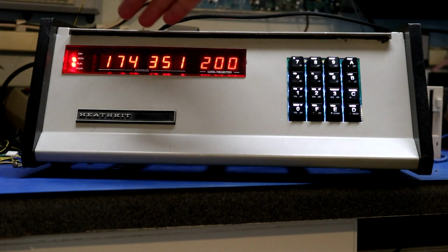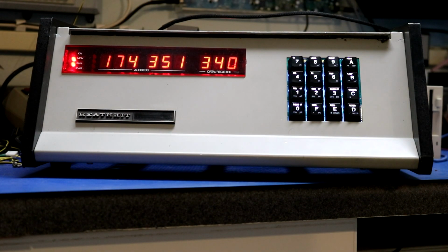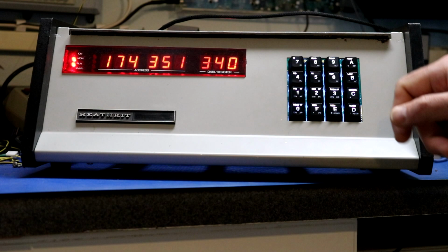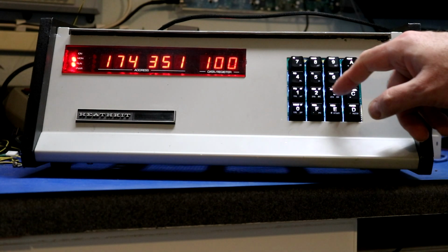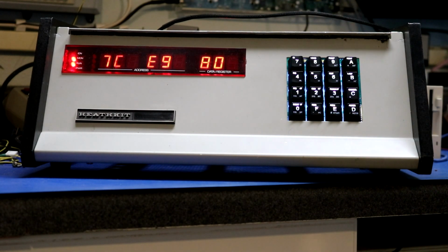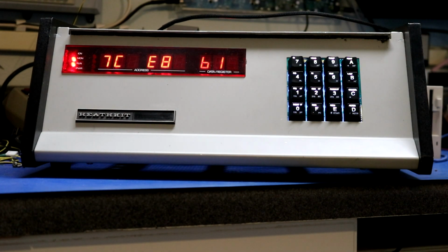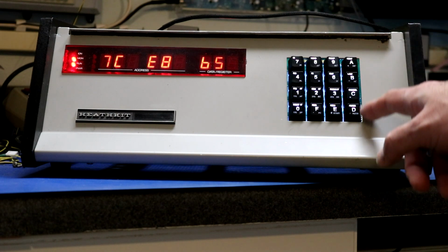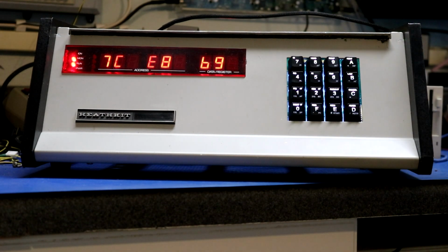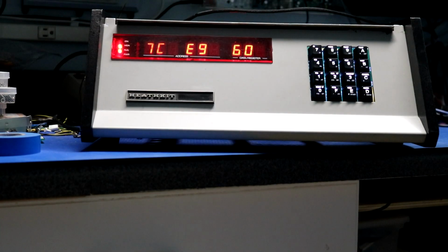Now, so far I've showed you this operating in octal mode, which is kind of how the original H8 worked. It's kind of an iconic thing that this thing was octal, but in later versions, Heathkit added a way to use hexadecimal, so I added that as well to my monitor. So if we go in here, we push the radix button, now it is in hex. Much easier to use. The keypad actually has hex digits on it so that we can pick a hex address if we want.